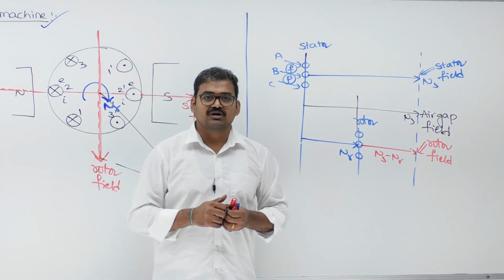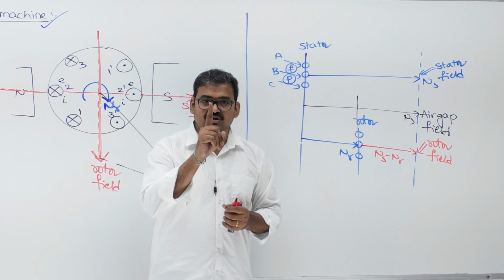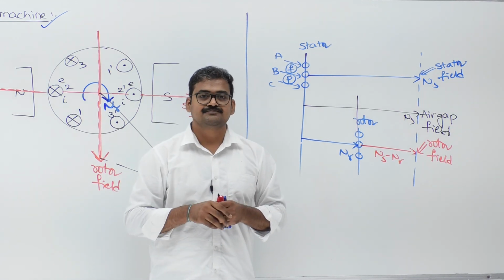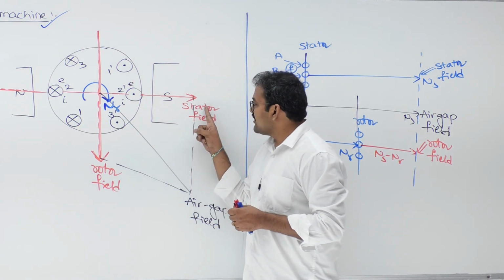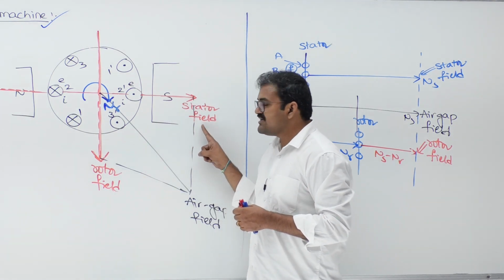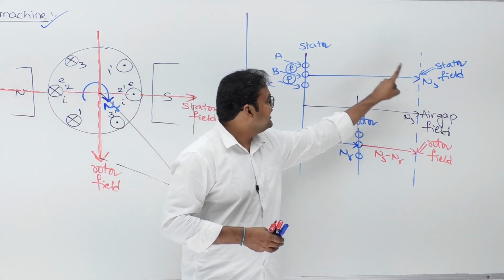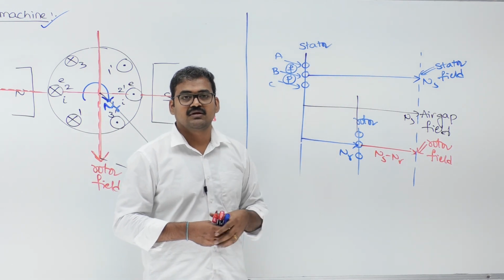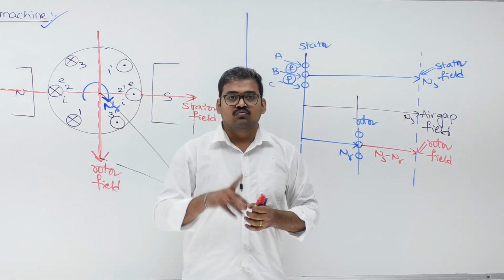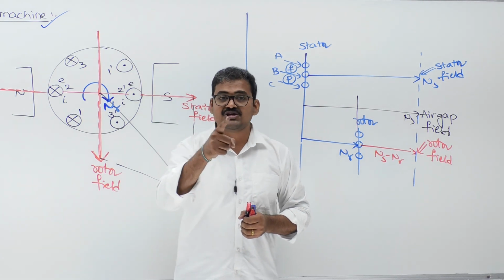Okay, question number 1. What is the speed of stator field with respect to stator in synchronous machine? Ns. What is the speed of stator field with respect to stator in DC machine? 0. What is the speed of stator field with respect to stator in induction machine? Ns.